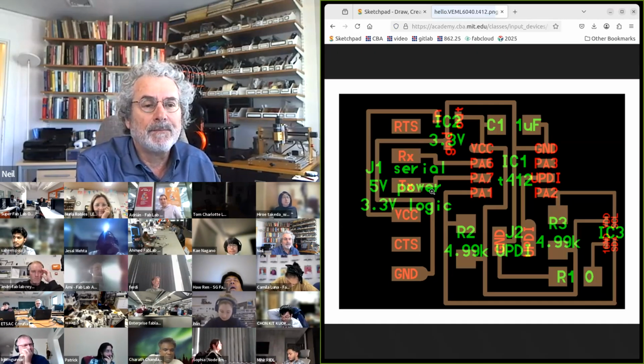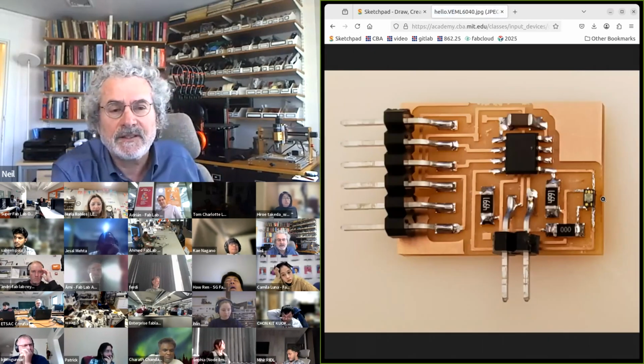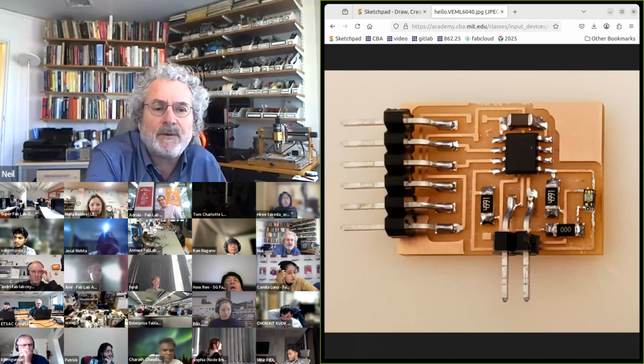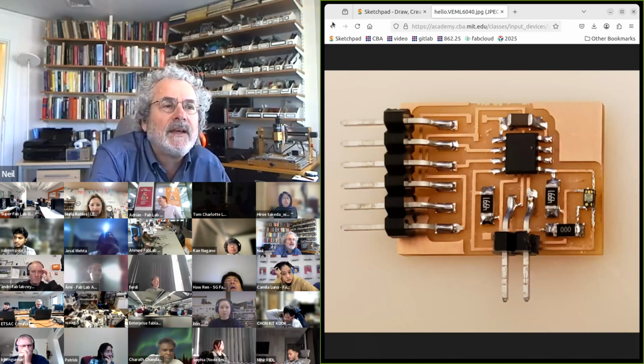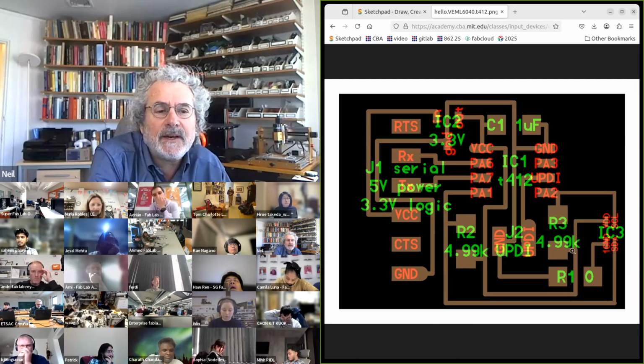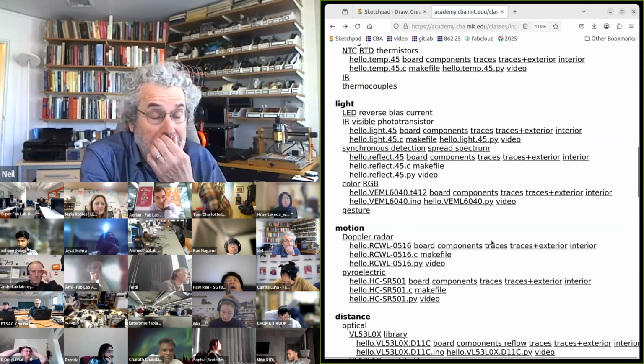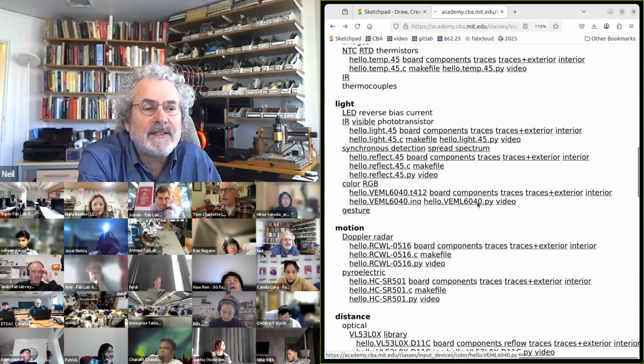And so here's the sensor. And this is an example where you have to do reflow with paste underneath it. And then this is an I2C device. And so I'm connecting SCL and SDA. And then it's reporting to me digitally.